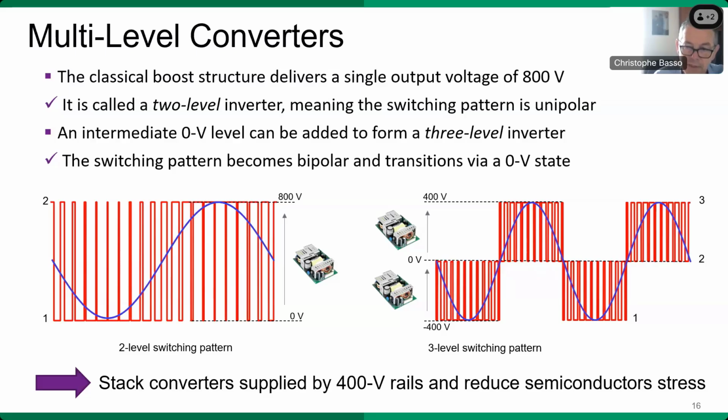In the three-phase application, the rectified voltage could peak close to 600 volts. So the DC bus is usually regulated at 750 or 800 volt. And you can imagine that this high level imposes severe breakdown constraints on the semiconductors and decoupling capacitors.